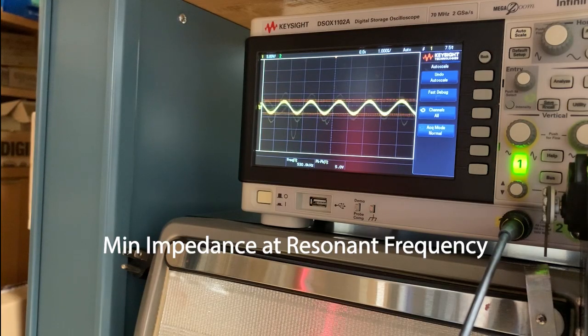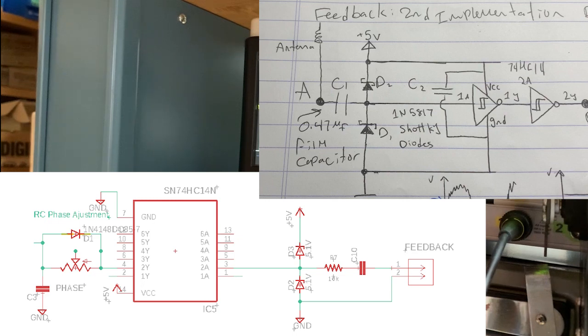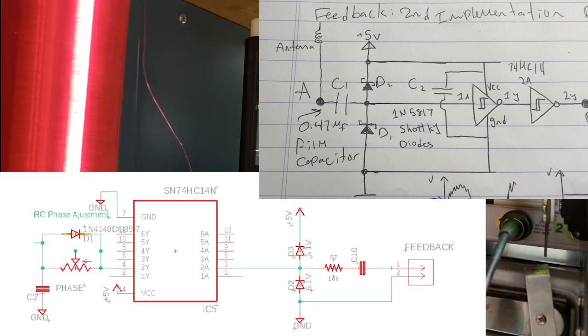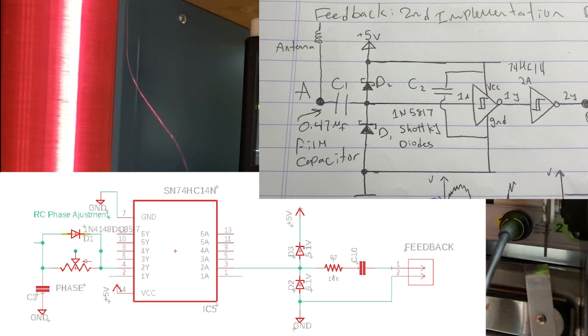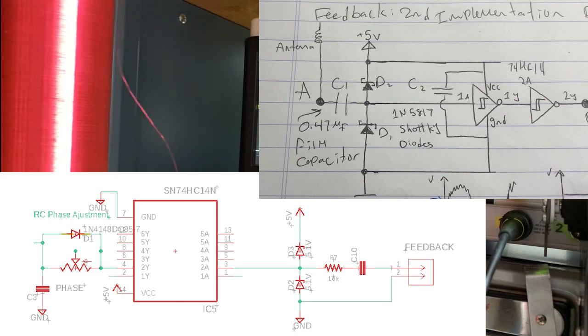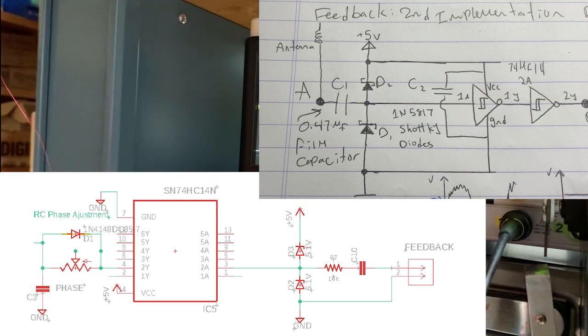The input stage of each driver must be driven by a signal with a short rise or fall time. Thus, the sinusoidal feedback from the secondary coil is fed through an SN74HC14 inverting Schmitt trigger. In the first implementation of this concept, a current transformer was used. The current transformer uses one turn of the secondary coil and around 80 turns of 24-gauge wire to reduce the current coming from the secondary to a more manageable level for logic ICs.